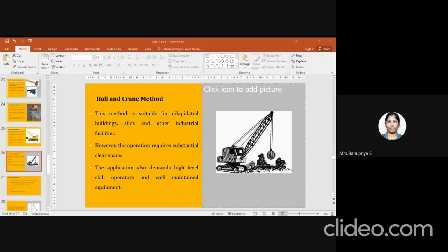After drilling, you clean the holes and inject the slurry at very high pressure. While injecting the slurry itself, cracks form all over your floor. After that, they remove the particular concrete component. So this is the step by step procedure they follow during concrete bursting, pressure bursting, or hydraulic bursting.